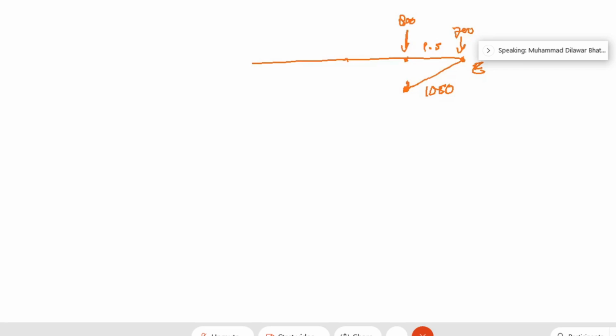And then we have another point, which is at point 800. Then we have another load of 1500. And we also know that at point A, there is a moment of how much? 9300. Therefore, this will go up till the moment of 9300. We know already that. But we want to calculate it while coming from E to A, while coming from this direction.